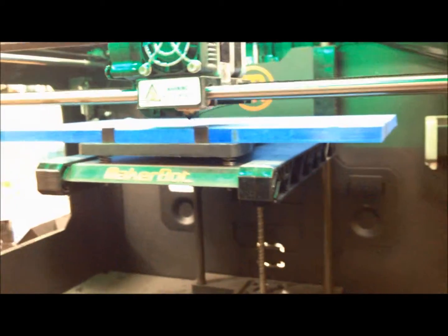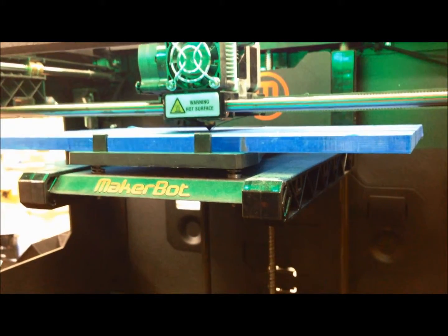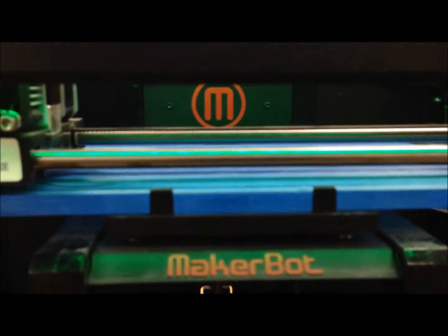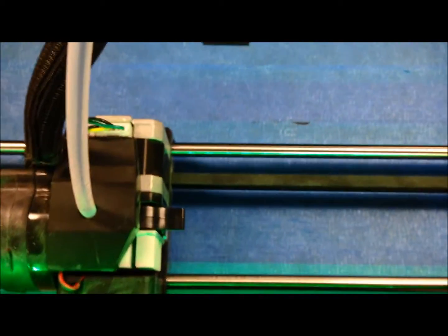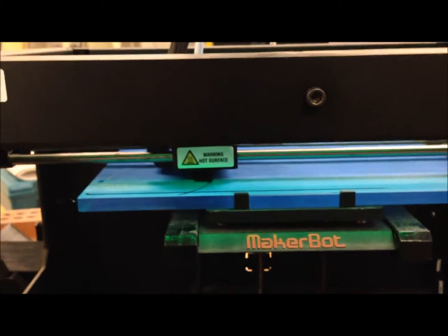This process is done mostly by the machine. All you have to do is follow the on-screen instructions and slowly turn the knobs on the bottom of the build plate until it is level at a good point. Once this is done, it is ready to print. To start printing, simply press the large M button on the machine and it will start going. You can tell it will start going because a green light will appear and you will see plastic start to be extruded onto the build plate.